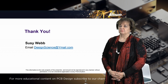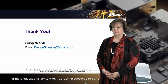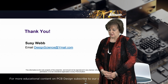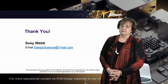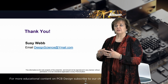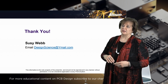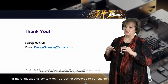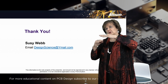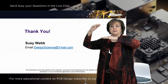The next question is by Lorenzo Carelli, asking, does EMI shielding make a big difference with high frequency signals? Yes, we would like to keep as much shielding as possible. I had a slide in there that showed that we would possibly put planes on the outer layer of the board, and that does help to contain that energy. As you saw in the early slides, there was one signal that was close to a plane on one side and open in air on the other side.